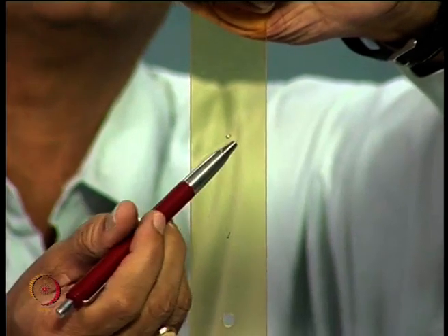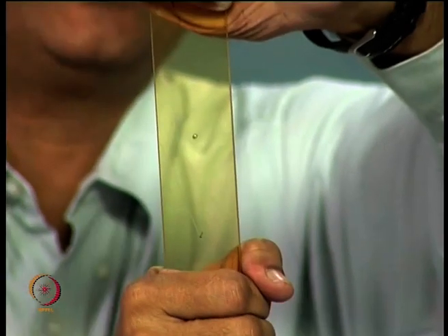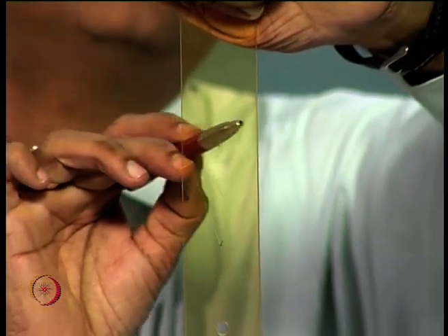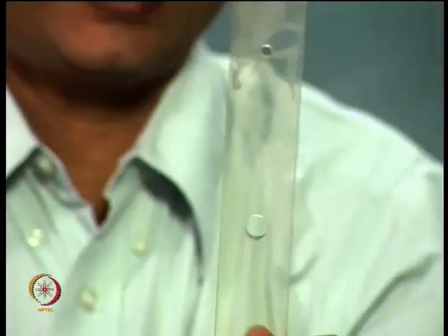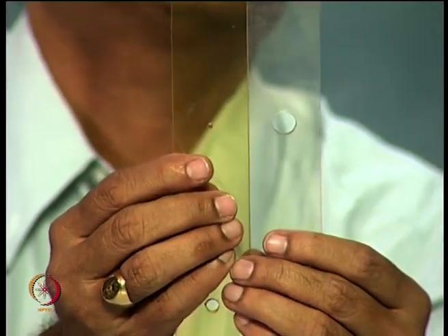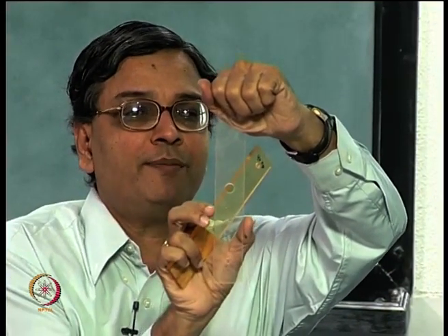From a mathematical point of view, it is possible to assume or idealize that this is a small hole in an infinite plate. Physically it is finite, but mathematically it could be modeled as infinite, and you would be able to find an analytical solution for this using theory of elasticity. On the other hand, if I take a model with a slightly larger hole, then this solution is no longer valid. The width is the same, in one case it is a very small hole, in another case the hole is about 10 to 12 millimeters, and this is comparable to the width. So, this becomes a finite body problem.